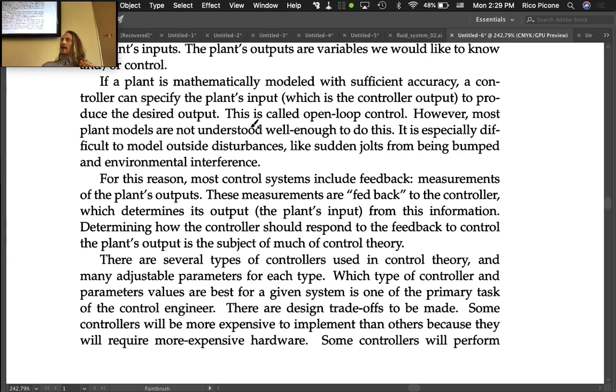One of the things in PID control is that it usually comes with three parameters that can be adjusted. So three gains, we'll call them. Even when you go down to the most simple, just the proportional controller, the P controller, you have one gain. But if you're using analog equipment, you can adjust those to an infinite number of real number values. So the gain could be like 52, but it could also be 52.00001, right?